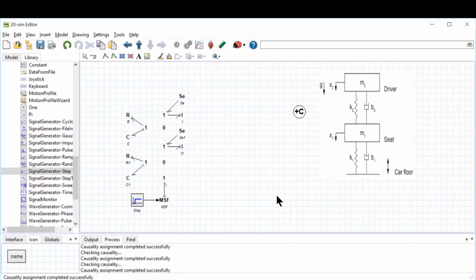Now, to have some visualization here, if I get rid of this connector for a second, see that there's a question how I am going to connect the remaining power bonds, and that is when this plus C comes into the picture, and of course the direction of your displacement in terms of coordinate system. So we have to connect them such that the bond graph representation is compatible with our assigned sign convention.